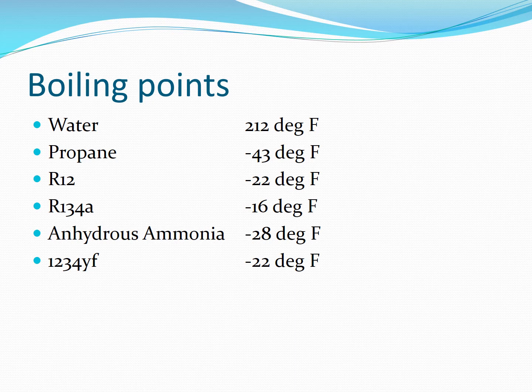I once saw a video that was put out by General Motors, and I cannot find it at this time, or I would post it. It was a video of a vehicle running with all the windows up and using propane as a refrigerant, and it had an evaporator leak, and they simulated a cigarette lighter being struck, and the vehicle immediately blew all the windows out because it had filled up the interior compartment with propane vapor, and it is flammable. So that is why we do not use that in the auto industry for a refrigerant.